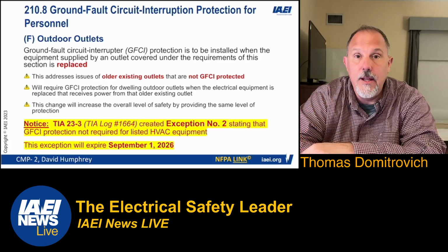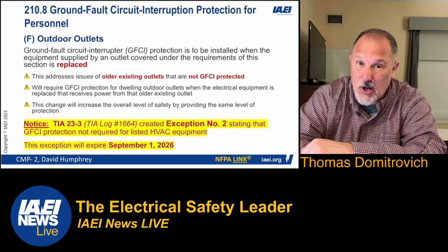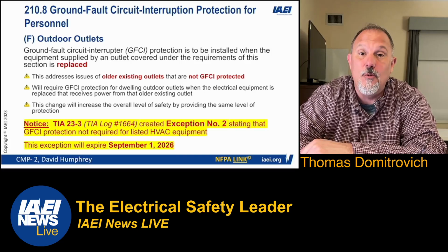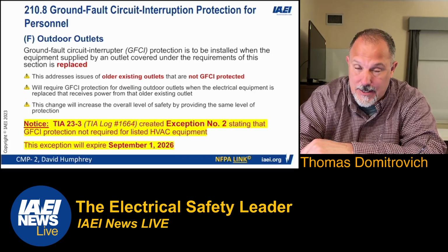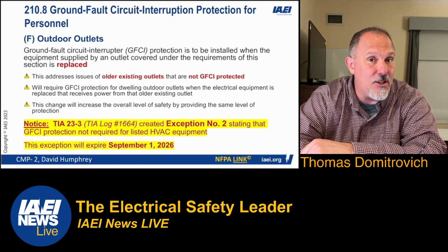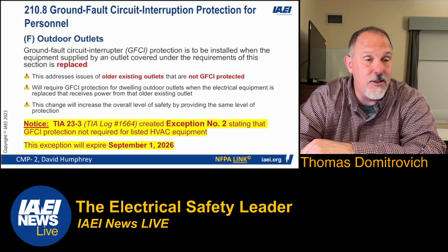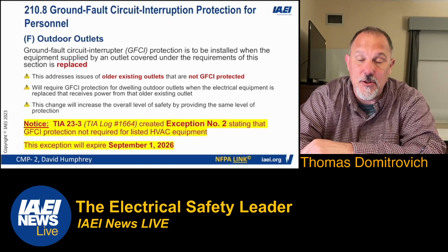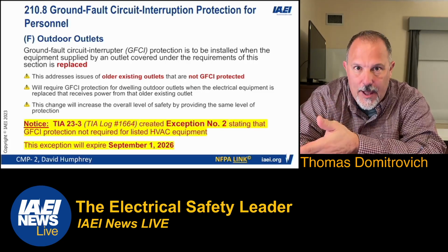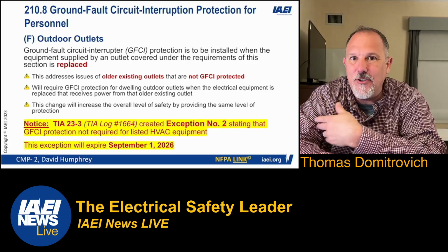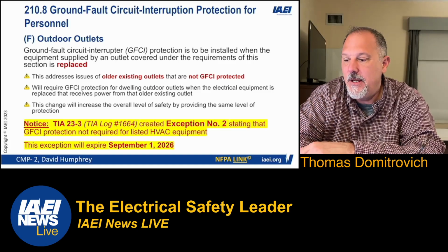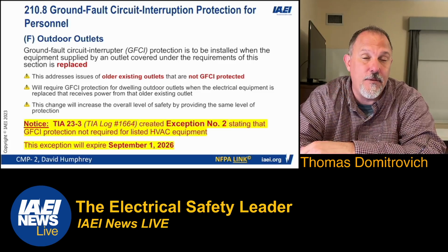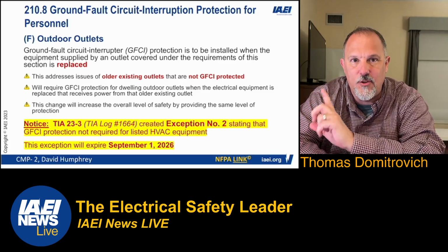And number two, if you have problems with 60 hertz leakage current or 60 hertz current returned on the equipment grounding conductor, violating Article 250, don't use that unit. Don't sell that unit. There are other solutions on the market that do not do that. It's not required for energy codes, etc. The variable frequency drives, well, that presents a unique challenge from high frequencies. That's what panel 2 agreed to.